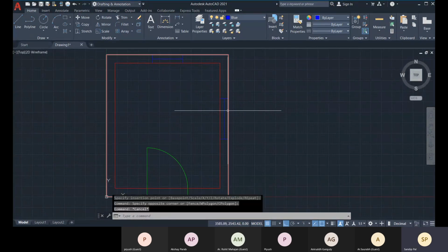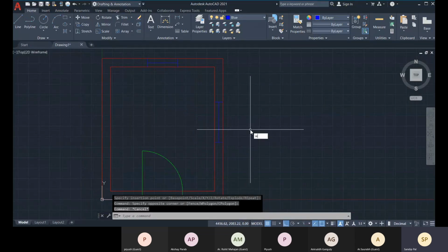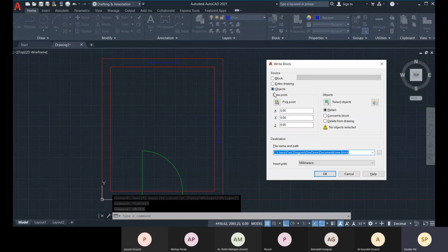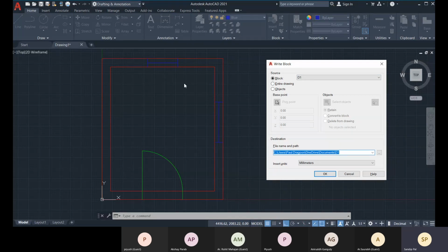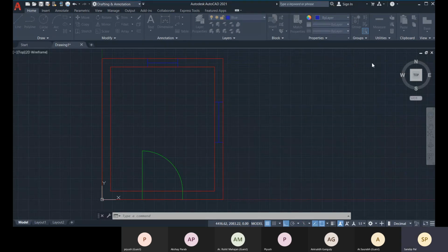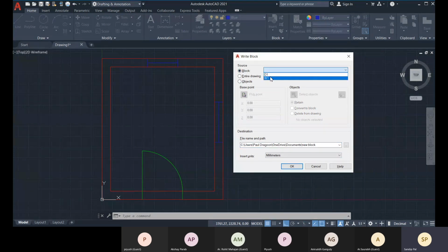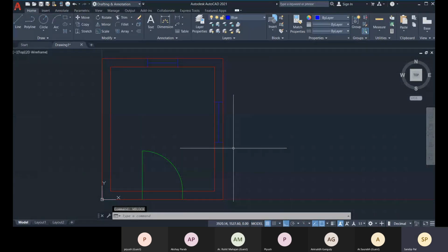And if you want to save this door and window symbol, you can use W block, that is write block. You can save your block as a drawing file. This block you have to select and give the name, but since you have already done the block creation, you select it. If you initially create with W block, you choose the object and, like selecting a block, pick points, and then give the name. Then I can define the path name, and in that folder it will be saved as a separate DWG file, and that DWG file can be inserted into a different DWG file and your projects.